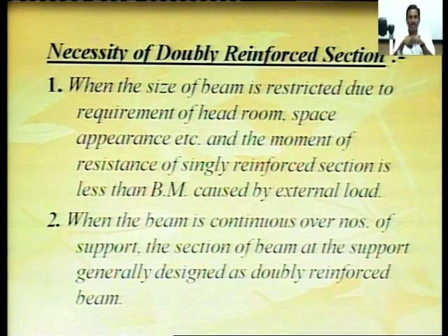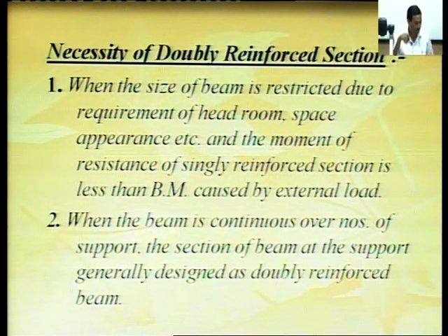Next topic is the necessity of doubly reinforced sections. What are the various necessities of doubly reinforced beam, or under what circumstances is a doubly reinforced beam required? First one is when the size of beam is restricted due to requirement of headroom, space, appearance, etc., and the moment of resistance of the singly reinforced section is less than the bending moment caused by the external load.